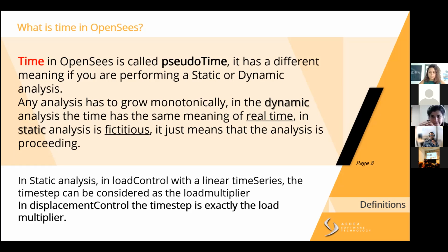So it's really important to reset if your pushover is the second stage of your analysis. For example, because pushover is one of the most common displacement control analyses in static that we do in OpenSees and STKO. So just remember this, it's important even if you're writing your own Python scripts.